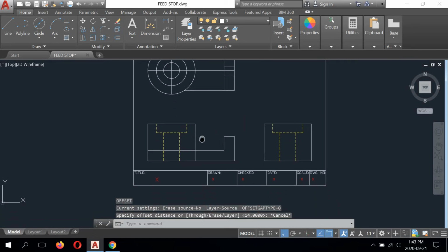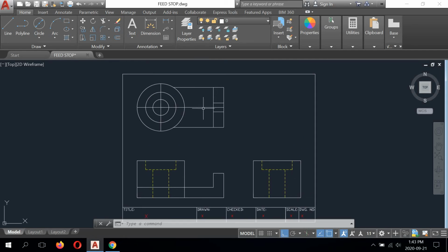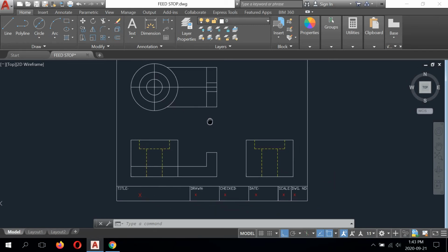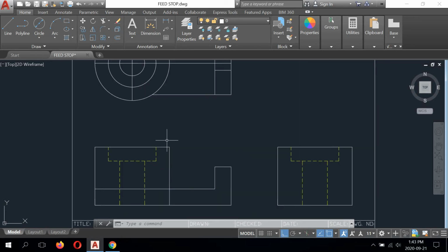All right. So this horizontal base basically runs into that cylinder, but there's no dimension on the drawing that tells me where it runs into the cylinder and where it begins. So I am actually forced to use the top view to help me finish this front view. I have to know where to trim this horizontal line off.